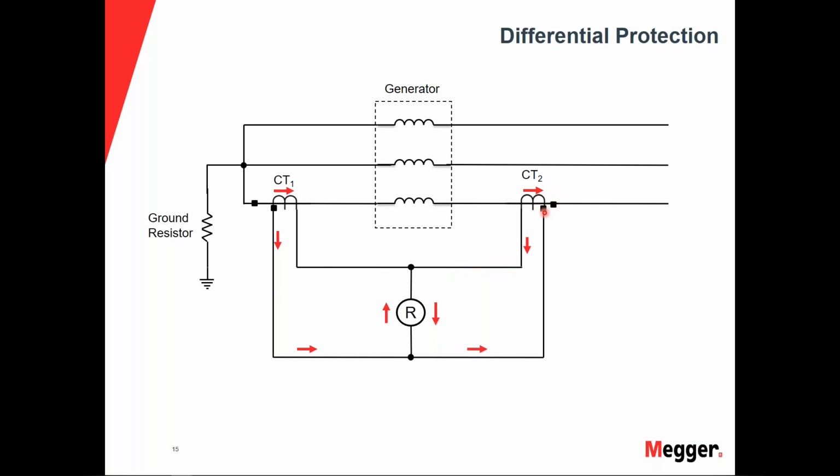As the current comes to the unit and comes back, we're flowing through the CT here, and you'll see the same amount of current coming across the relay as well. Now these two currents coming into this CT are going to equal 0. I1 minus I2 will be 0 across this relay, so therefore everything will look proper, everything will function properly, and everything is good.